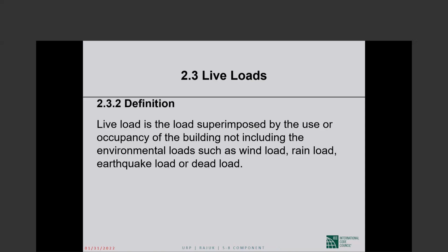Everything else, absolutely everything else, all the other loads are parasitic loads. Dead load is the first one. In order to impose live loads on our structure, we have to design to carry the weight of the structure, which is much more than the live loads, but we have no choice. Wind is a parasitic load that's always present. We have to do something about it. Otherwise our structure will be blown away. So that perspective is important.